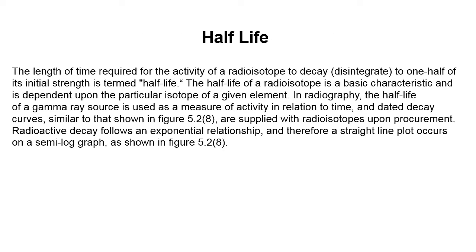Half-life. Half-life is the length of time required for the activity of a radioisotope to decay, disintegrate, to 1/2 of its initial strength. The half-life of a radioactive isotope is a basic characteristic and is dependent upon the particular isotope of a given element. In radiography, the half-life of a gamma source is used as a measure of the activity in relation to time, and dated decay curves similar to that shown in figure 5.2.8 are supplied with radioisotopes upon procurement.